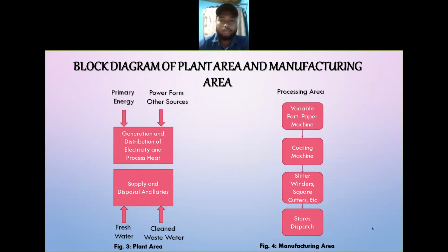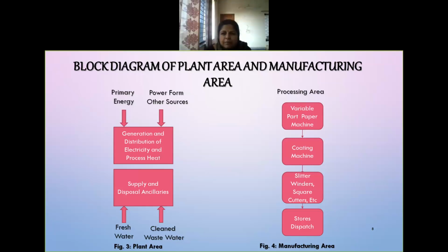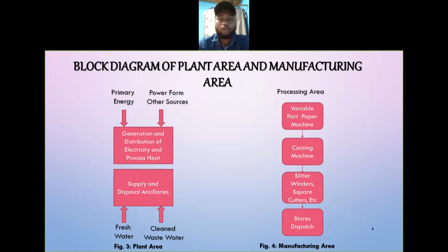It is stored in one of the containers for several days, where the pulp settles down and the water rises to the upper level and can be extracted out. The liquid pulp is rolled over the pressure rollers and suctions, and it is dried at several temperatures. It also passes through the cylindrical rollers to obtain the paper. Next slide.